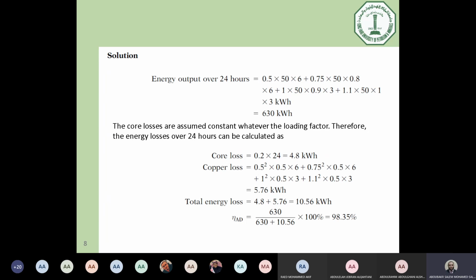And you can feel that in the power supplies which are based on transformers, the chargers or small adapters. If you plug the adapter on the supply and remove the socket from the load, and stay for several minutes or 1 hour, you will feel that the adapter is hot, even if there is no load. This is because there is internal core loss on the small transformer inside this adapter. So core loss exists all of the time.